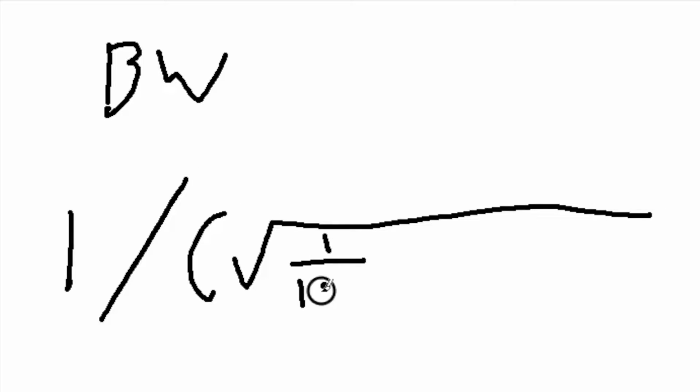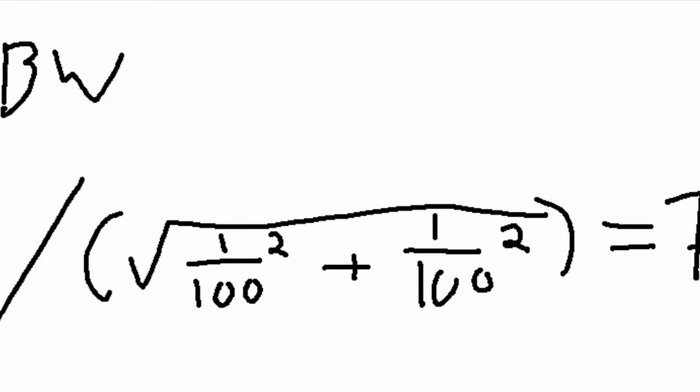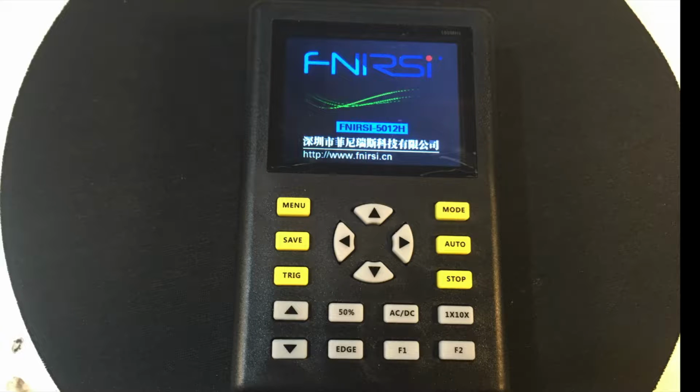So if we take our bandwidth of the entire system, since these are cascaded, we're just doing 100 and 100, which means that we're going to result around 70-ish, a little more than 70 as far as our bandwidth goes. Unless they're giving you a higher bandwidth with the hardware than 100 megahertz, and then that would even it out with the 100 megahertz probe, but it'd have to be like 350 megahertz or so to make that negligible. Or they were artificially increasing the gain above certain levels, which is also possible trickery.